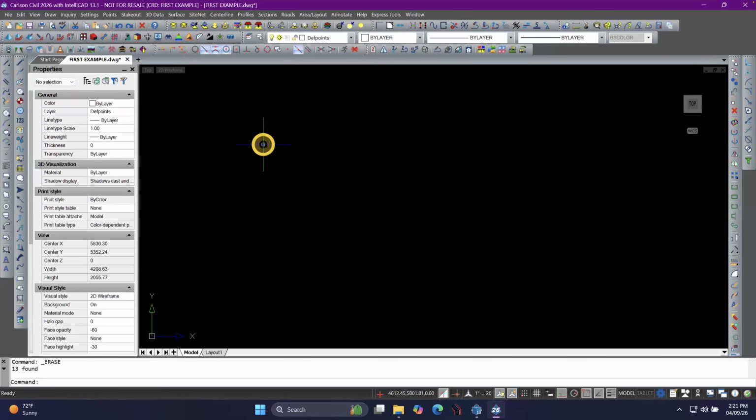Okay, so now let's talk about some of the draw tools that we have. Here on my menu, I use this one all the time, 2D polyline. I use draw a 3D polyline quite a bit. Here's circle with the center radius. And notice there's a little black arrow at the bottom corner.